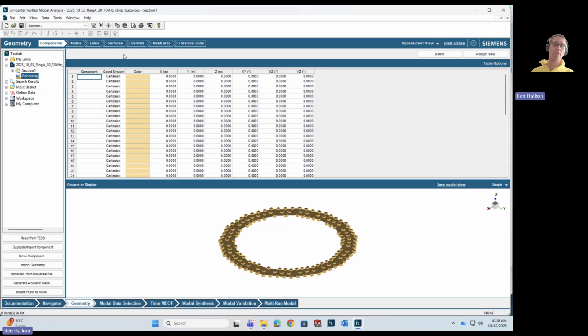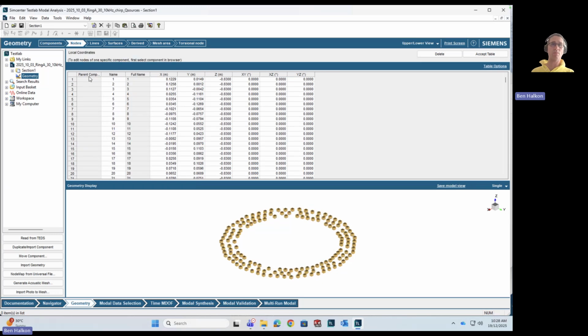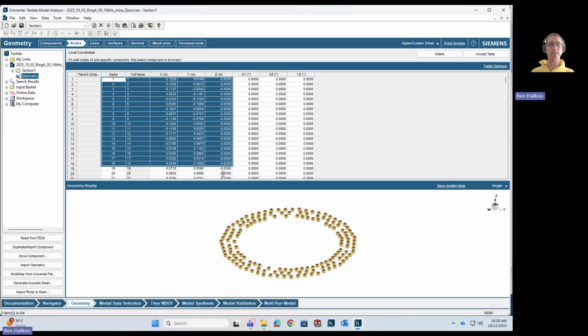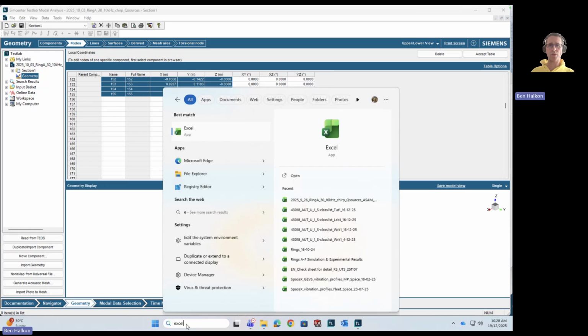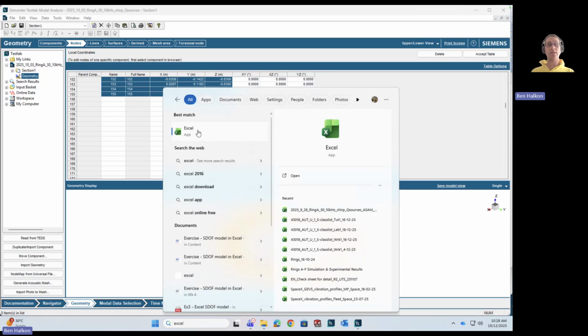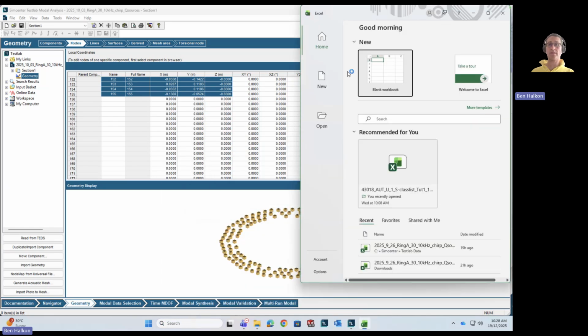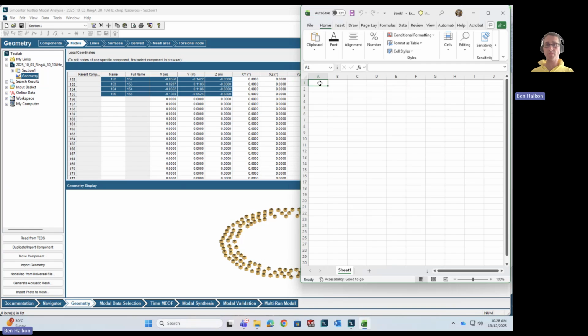what we're missing that we need in Simcenter Testlab when we build a project from scratch, or when we do a modal acquisition campaign within Simcenter, is that we identify a component. Then for each of the components, we have a list of node names and XY data. So that information comes through, the node names and XY data, but we don't get a component name. So we have to use a workaround to resolve this.